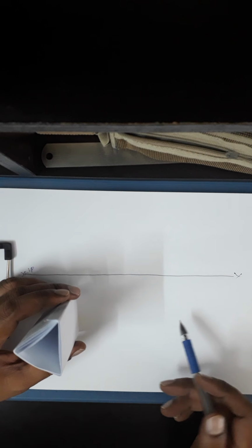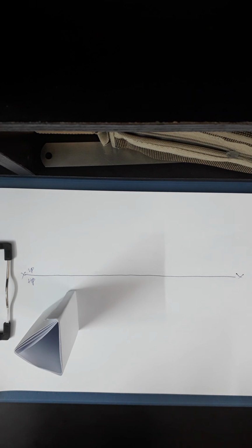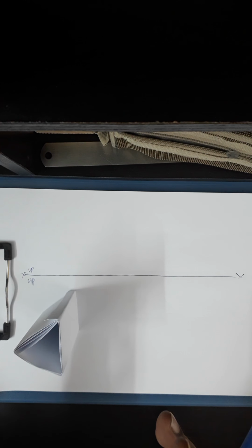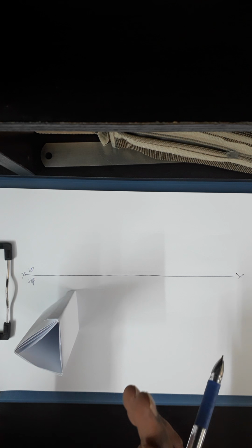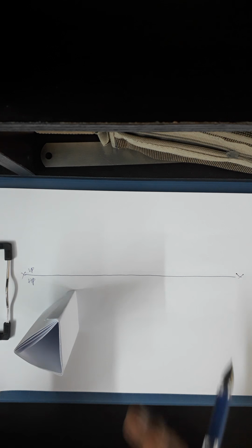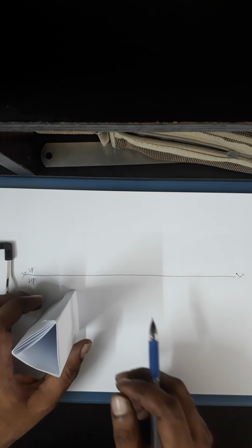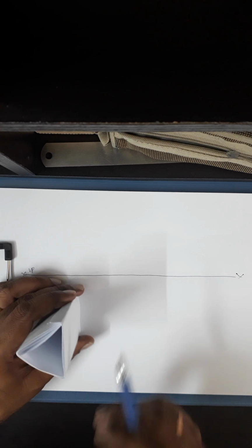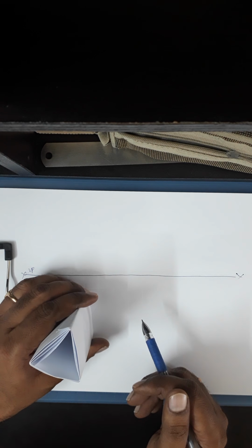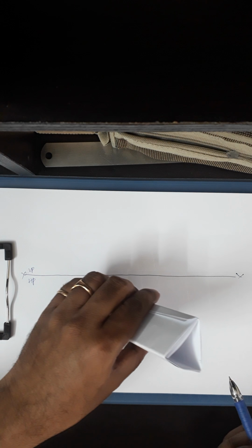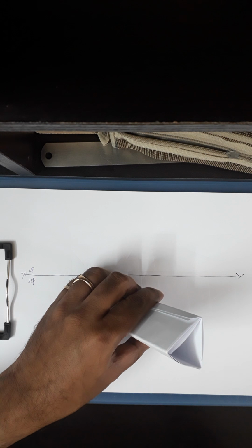Okay. So when you read the sentence, you find out whether the solid is resting on its base on HP, or resting on one of its base edges on HP, or resting on one of its base corners on HP. Based on that, I have to draw the first view. Because when I draw the first view, always you're going to keep the solid resting on its base on HP. Then I'll change the position in the second step, so that I can satisfy the condition he has given.